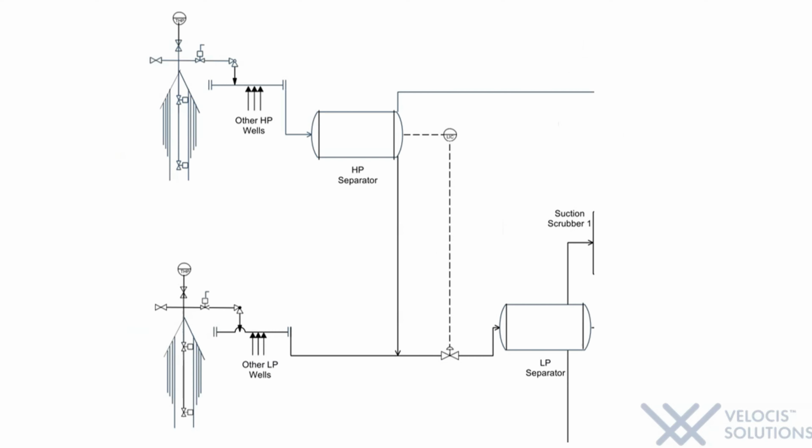In our Zafar platform, two-phase mixtures from LP (low pressure) and HP (high pressure) manifolds enter corresponding separators in order to remove the liquid and gas parts of the mixture from each other. To be more precise, the mixture entering the HP separator, working at 40 degrees Celsius and 2901 kilopascals, is processed under high-pressure conditions, and then its depressurized liquid from the bottom part of the column comes into the LP separator working at 35 degrees Celsius and 1401 kilopascals.